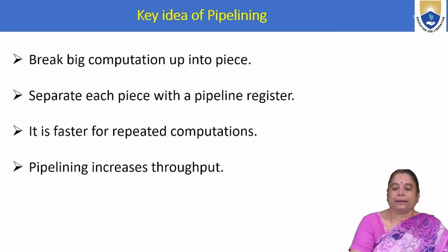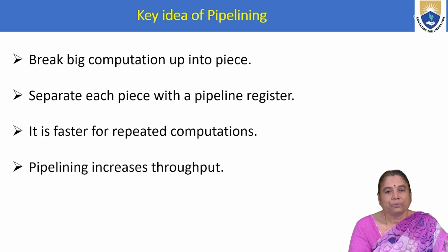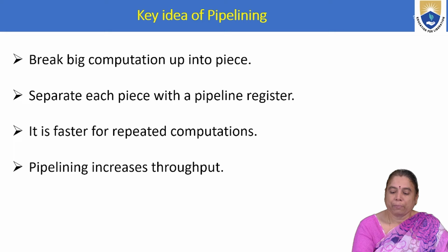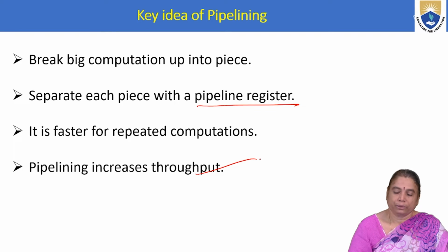What is the key idea behind pipelining? Breaking a big computation into small pieces, and separating each piece with a pipeline register. It is faster for repeated computations. Pipelining increases throughput.